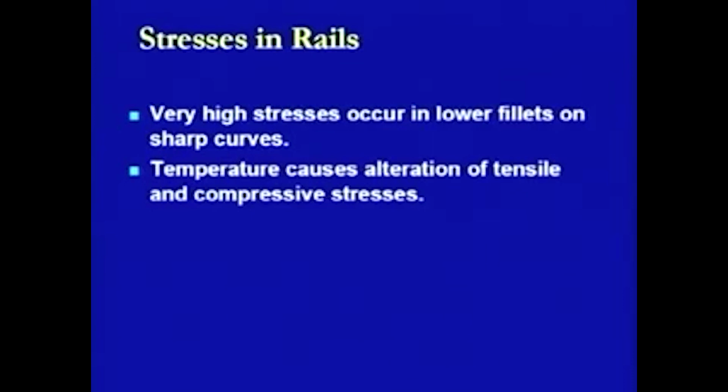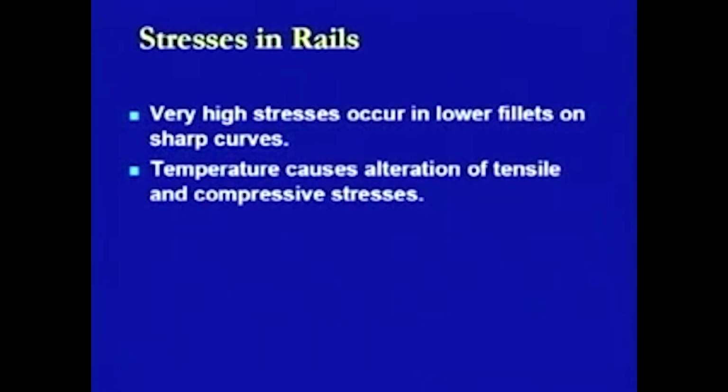Then the other thing which has already been discussed is the temperature variations. As has been told to you, any track which is placed, is placed at a certain temperature. Now, if the temperature goes below or above this temperature, it is going to create an effect in terms of either contractions or expansions, depending on the variation of the temperature. As soon as this type of variation is there, it is going to create tensile stresses or compressive stresses in the system.